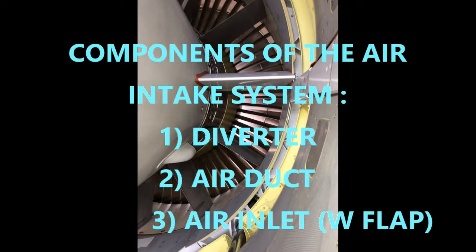Your diverter is installed just forward of the tail cone, at the bottom of the rear fuselage. What is this here for? The diverter's diverting the air. It's improving that ram air recovery in flight, when it's operating in flight. And like I said, you've got your inlet body, and you've got your hoses, housing, and different little pieces in there, seals and whatnot, as part of that.